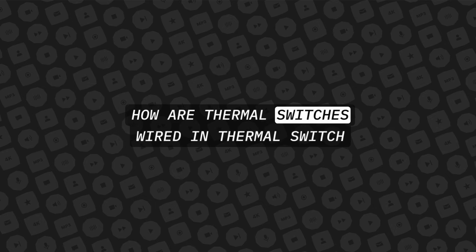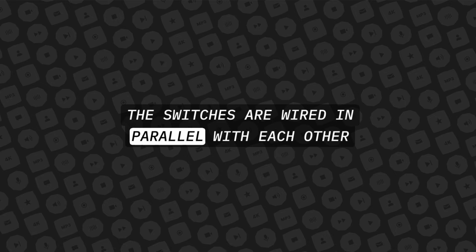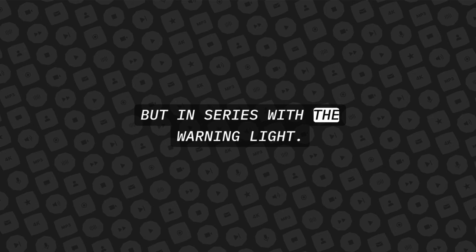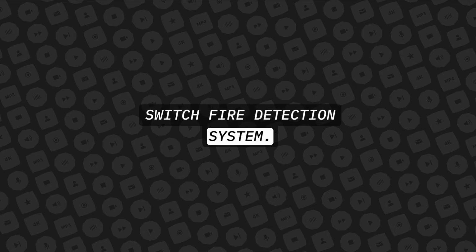How are thermal switches wired in thermal switch fire detection systems? The switches are wired in parallel with each other, but in series with the warning light. Describe the operating principle of a thermal switch fire detection system.